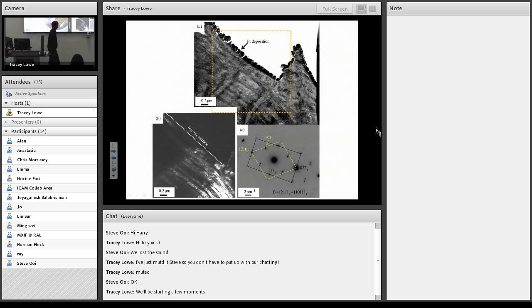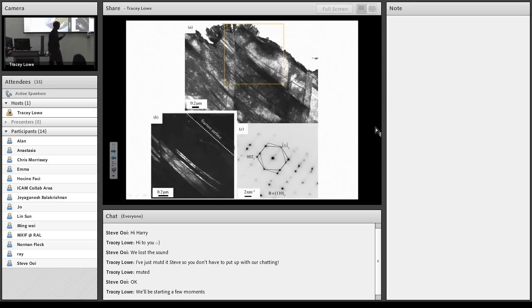And it turns out, in the case of the epsilon martensite, that the facets tend to be parallel to the habit plane of the hexagonal martensite. In other words, we've got the hydrogen going to those interfaces. And in the case of the high aluminium alloy, parallel to the twin interfaces. The twinning is less sensitive to fracture than the epsilon martensite. So the effect of aluminium in this case is simply to alter the stacking fault energy to eliminate the epsilon martensite and also to reduce the amount of mechanical twinning.